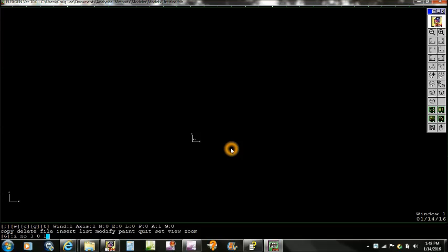So we're going to input a node at a diameter or a distance of 3. Y is 0 and X is going to be 1. So there's that. We do one at 0 and we do one at -1. So the thickness on the inner diameter is 2 inches. And now we go to the outer diameter, which is going to be 12 inches out. It'll be tapered, and it's only going to be ½ an inch thick out there. So we're done doing that.